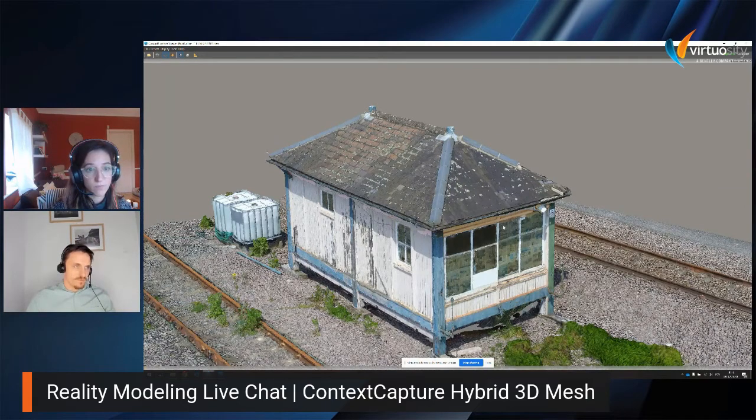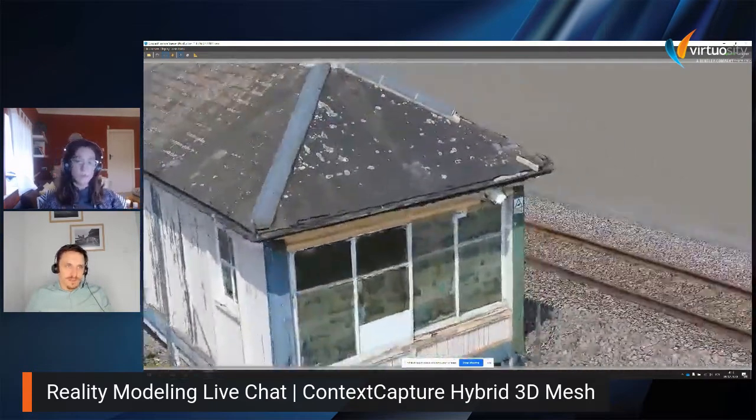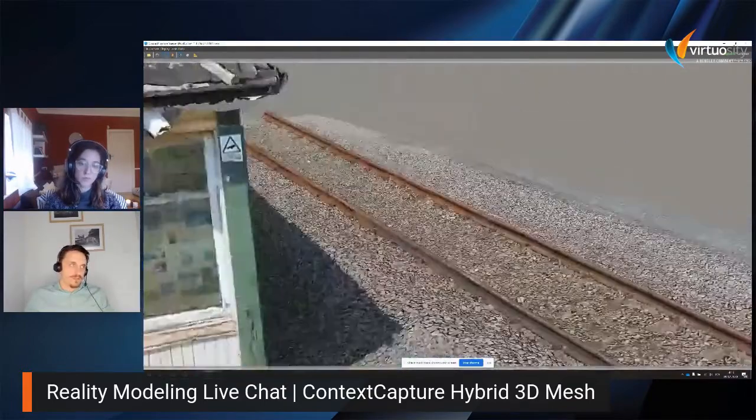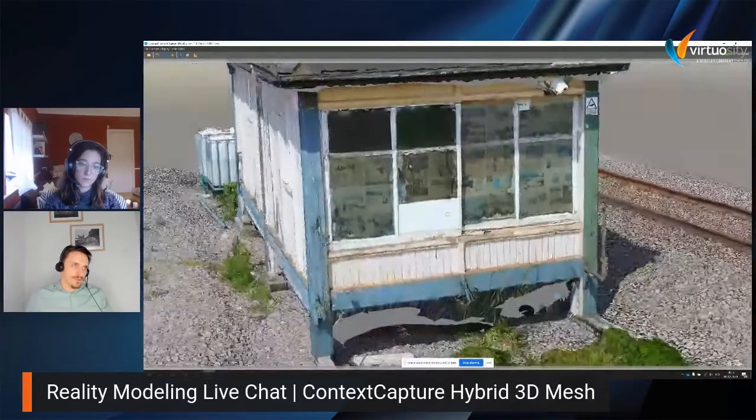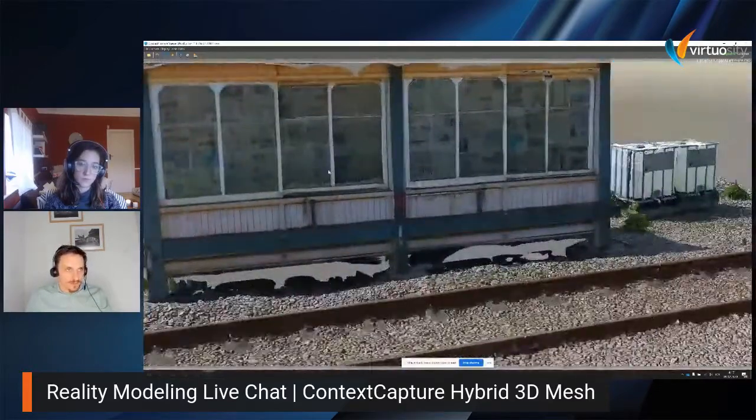The main advantage is that we are taking the strong side of the point cloud, which is the accuracy of the geometry and gathering the details, especially of thin structures like pipes, thin beams and metal plates. And we are taking the stronger part from photogrammetry, which is the color and texture information. We connect those two, and that's the main advantage here. We can, for example, collect more picture information.